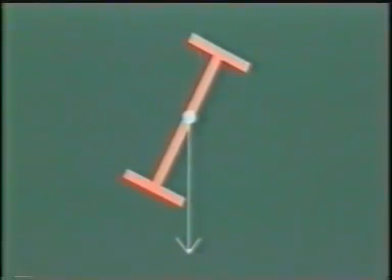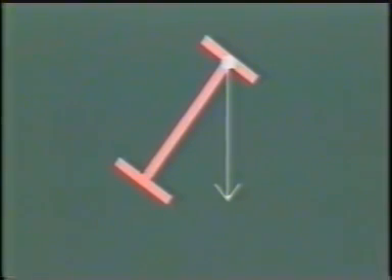One feature not mentioned so far is the level at which the load is applied. Consider a cantilever, such as one of those shown earlier, with the load applied through the centroid of the section. This may be regarded as the standard reference position. However, it can be seen that if the load is applied at the level of the top flange, then it exerts an additional overturning moment, which clearly enhances the torque and causes less favourable conditions.